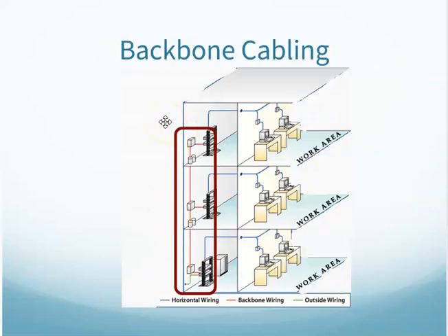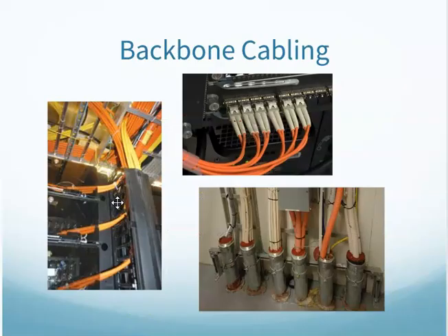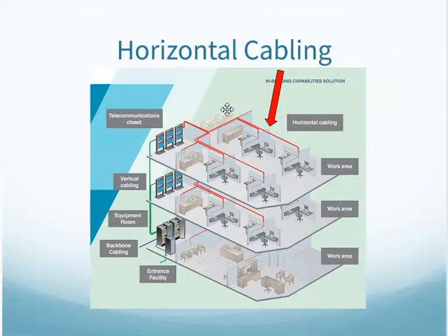That is the interconnection point between the backbone cabling, most likely the fiber optic cabling connecting from floor to floor, going from switch to switch. And actually we're seeing here the fiber optic cabling between the closets, switch to switch. This is the type of cabling we'd be finding, fiber optic plugged into our switches, probably down through conduits in the floor, fire stopped as it goes to the other closet below. And then interconnecting with our horizontal cabling, the copper cabling from the workstations back into the closet into the patch panels.